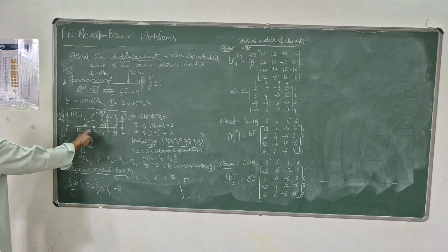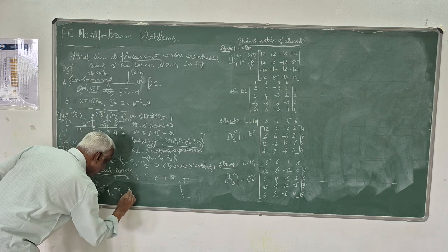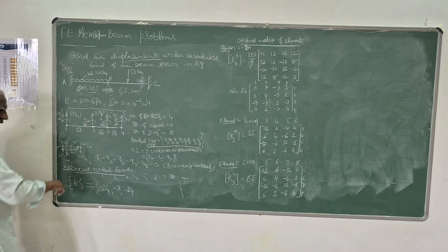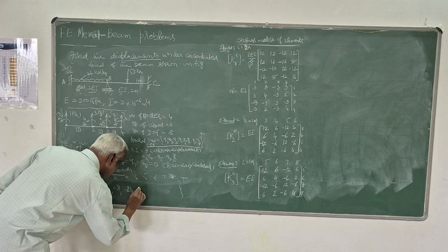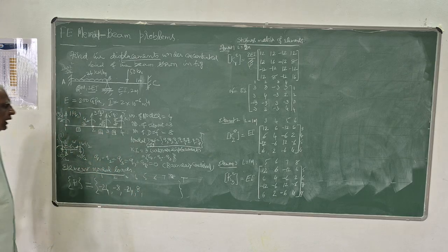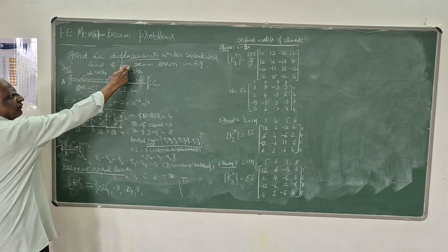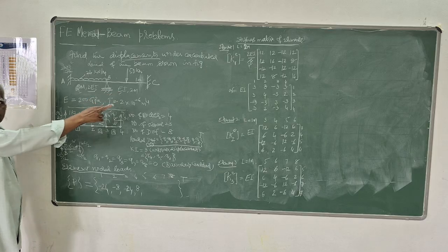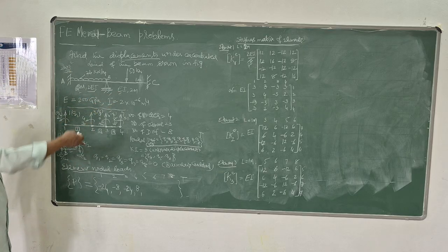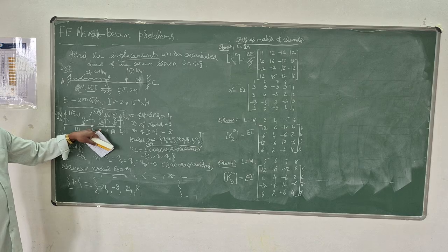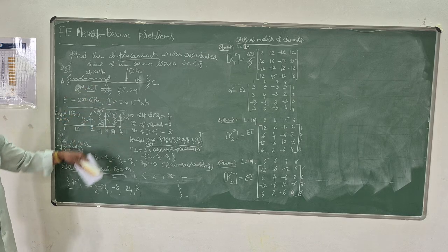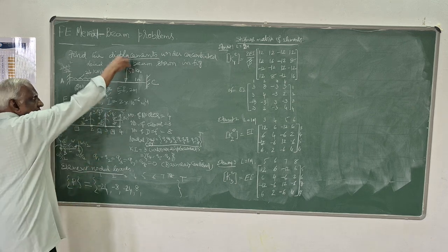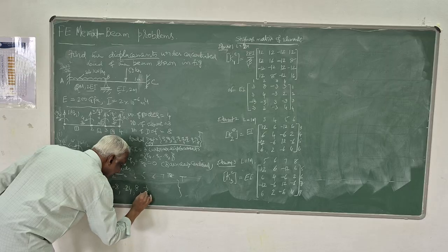Then third degree of freedom, again it is minus 24, because it is WL by 2. This is anti-clockwise moment, so it is plus 8. And at fifth, we have concentrated load given exactly corresponding to these degrees of freedom. That's what I showed. Whenever the concentrated load or moment is given on the member, you select a node there and express that degree of freedom there, so that we take care. So since it is acting down, we take it as negative.